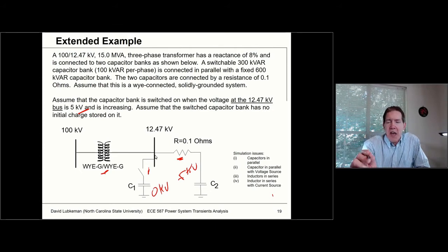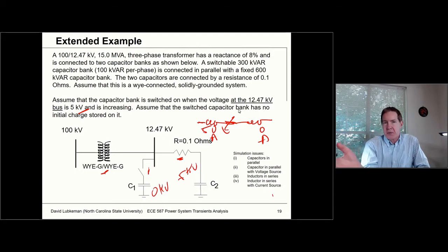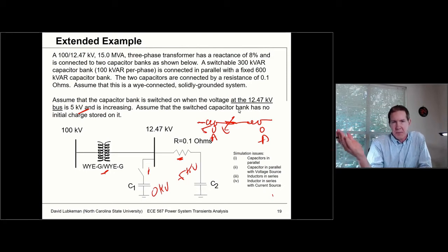But anyway, if you had also a situation where you had two inductances, and let's suppose this initial value were, like, say 50 amps, and this initial value were 0 amps, well, we can't be connecting these two devices together in series either, right? Because the initial conditions wouldn't correspond to each other. There'd be a conflict.